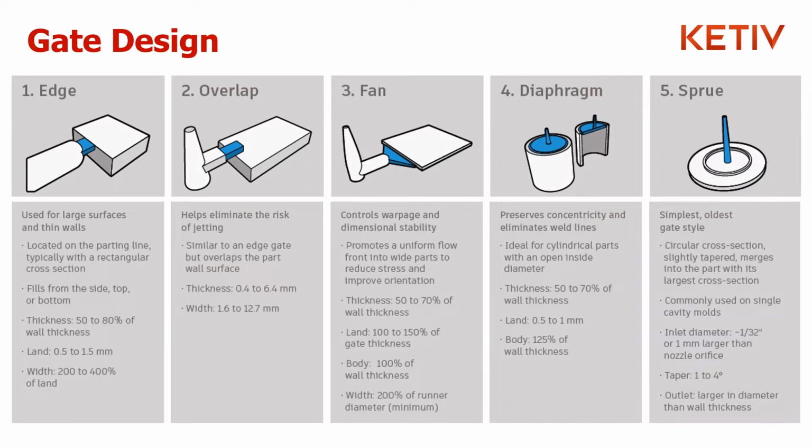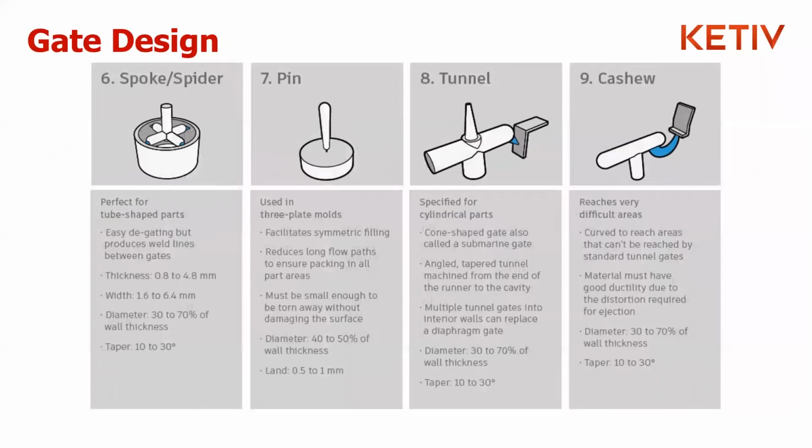And you might be missing a different cooling approach, a different gating approach that really gets back to what we need to explore for the part functionality, performance, quality criteria, as well as the individual ingredients going in. For example, material: is that material shear sensitive or color combination sensitive to shear rate, shear stress? Sometimes you might be over the guideline limit and get away with it. In a lot of cases you are. In some cases you might need to go well below the guideline for shear rate, shear stress to not see cosmetic issues like blush.